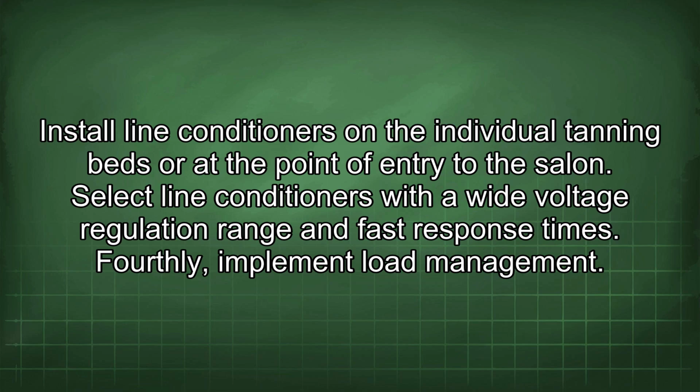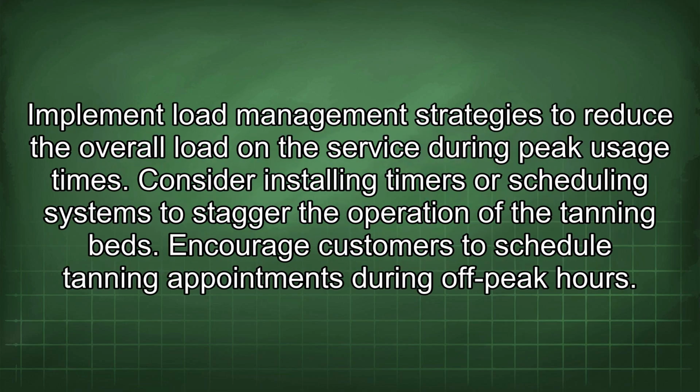Fourthly, implement load management. Implement load management strategies to reduce the overall load on the service during peak usage times. Consider installing timers or scheduling systems to stagger the operation of the tanning beds. Encourage customers to schedule tanning appointments during off-peak hours.